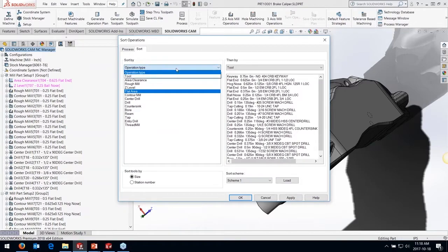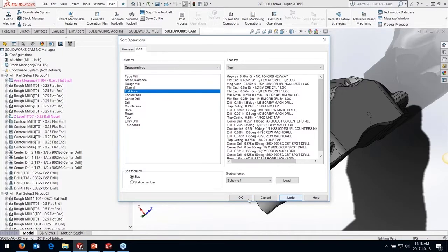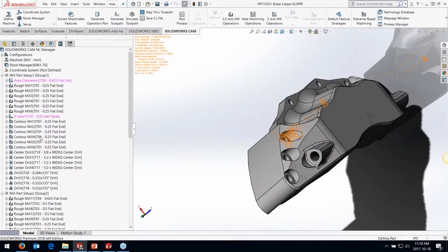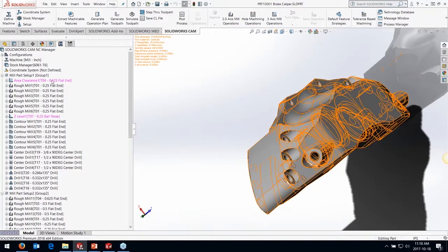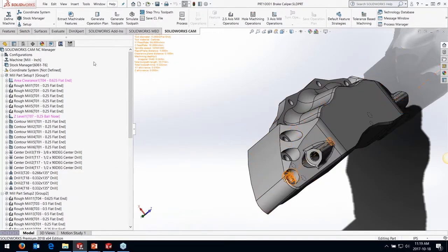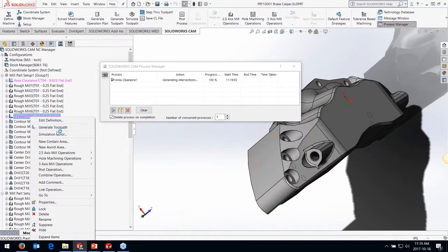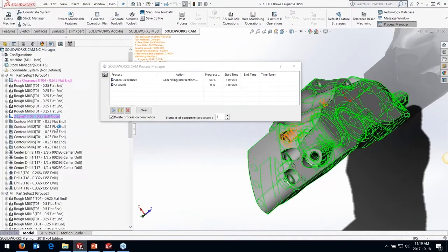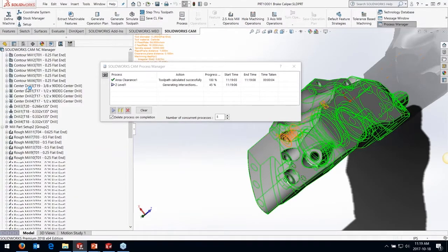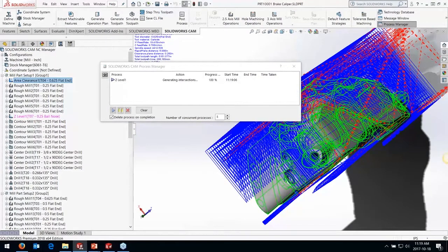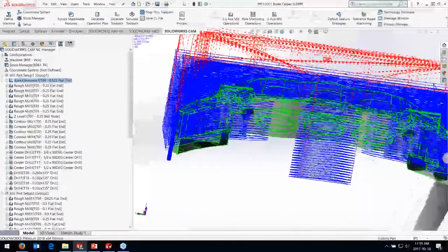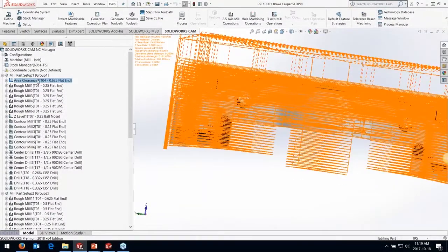So I'm just going to go in and basically rough this out here, do a Z level to clean up this tapered section here with a big radius down at the bottom here. And then we just select our faces to machine and generate the operation plan. Again, I can save strategies to it for 3-axis. I want to do that rougher first, obviously, before I go and start machining the other geometry.